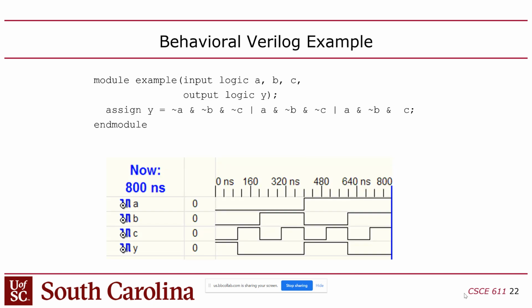Okay, but speaking of simulation, when you simulate this, what do you actually see? Obviously there are no print statements in there, there's no graphics involved, there's no console, right? What are you actually looking for? Well, generally speaking, the simulators put out, as I mentioned earlier, a timing diagram, which is meant to look like a scope, an oscilloscope. So the horizontal axis here is time. You notice that it starts at 0 nanoseconds and goes up to 800 nanoseconds, right?